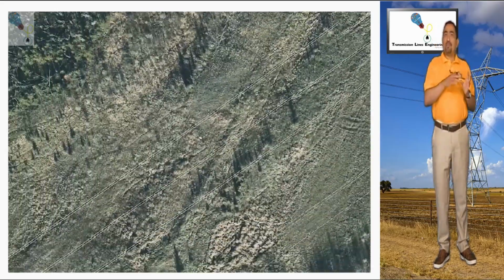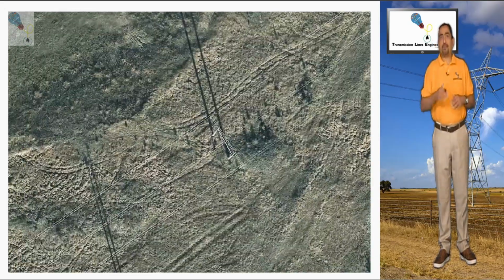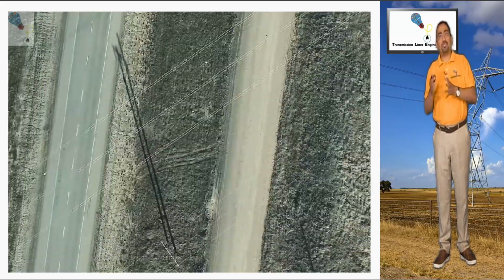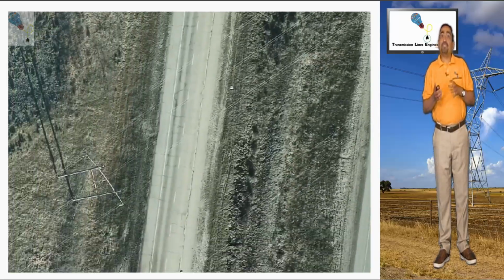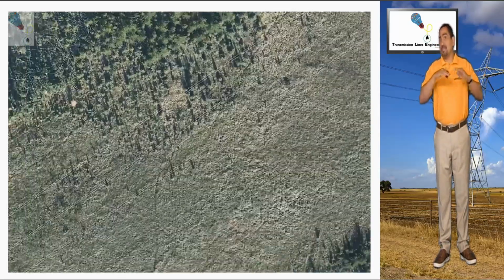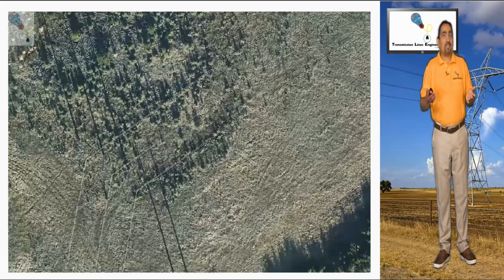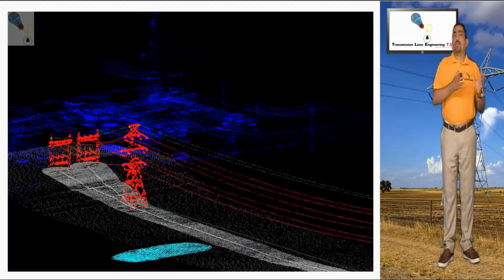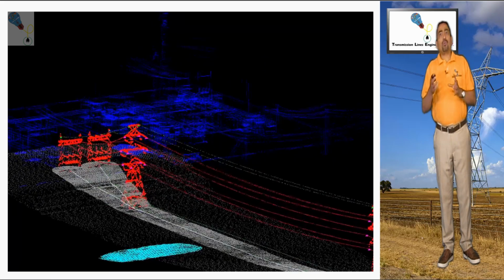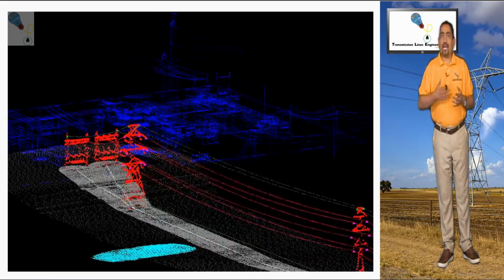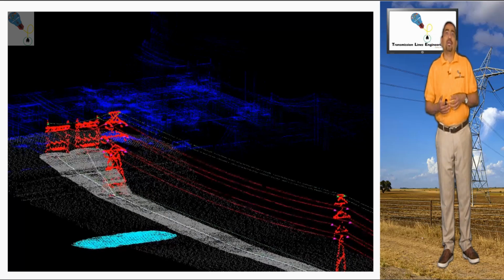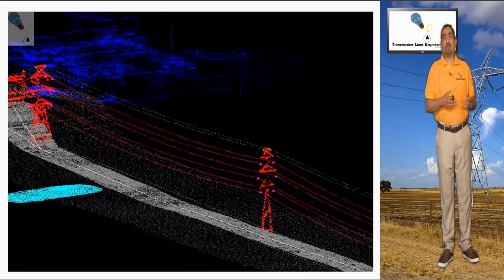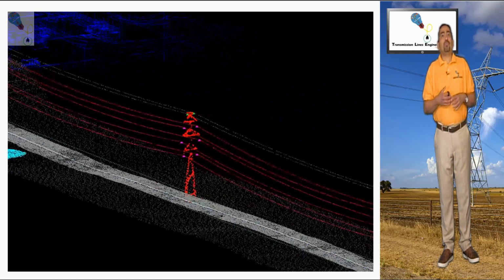Photogrammetry, when taken from a few meters above ground, has both better resolution and positioning accuracy, and if these images are mounted as a layer on a LiDAR file, the results are simply spectacular. With a LiDAR survey, it's not required that the staff is in danger when accessing difficult areas. The number of points recorded is much higher than those taken with a total station, and you can have a